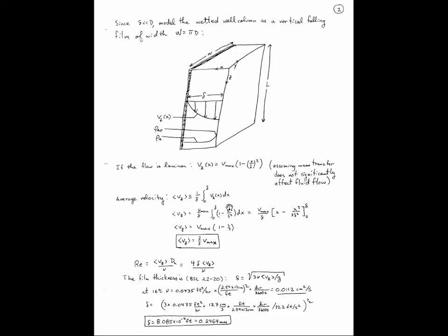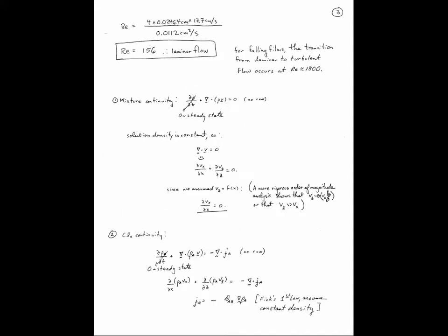It's very typical in these problems to assume that the bulk of the velocity in the z direction is due to the convective flow, gravity-driven convective flow of water, and so that Vz depends only upon x and not upon z. In other words, you don't absorb enough chlorine from this gas phase to markedly change the velocity of the water, and that would be typical of the way these gas absorption towers would operate.